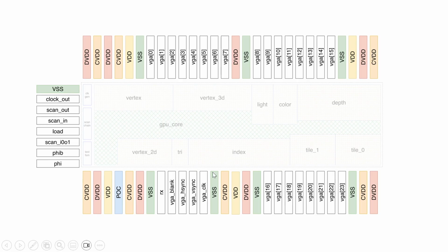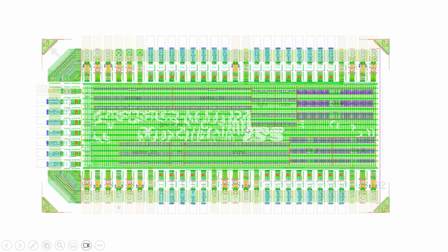For placement, we just equally distributed the power pads everywhere to ensure enough current for every pad. And we inserted the ground pad between the signal output sets to improve signal integrity. And this is the result after the place and route process and after the seal ring and dummy filling.